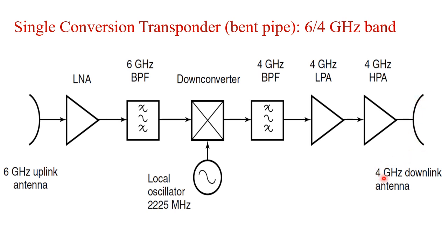That is why if we use 4 gigahertz frequency at downlink, the same antenna will work, because the objective of the downlink is different from the uplink. Get my point? For uplink, it has to be pointed towards the satellite only. But for downlink, it is not intended to contact a certain point. It is trying to broadcast over a region of space on Earth. So obviously we don't require a high gain antenna. Okay, so 4 gigahertz will work.